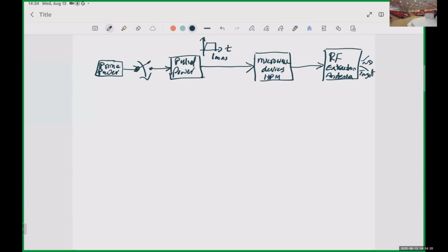But for shorter pulses, now we are talking about megavolt or MeVs and kiloamps of current, not megaamps of current, in your pulse. Now it's gigawatts of power. That's what you drive your high power microwave source with. And when I say high power microwave source, this includes the electron gun, or your vacuum anode cathode setup, the anode cathode gap.